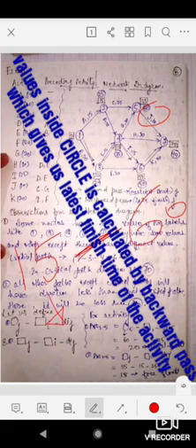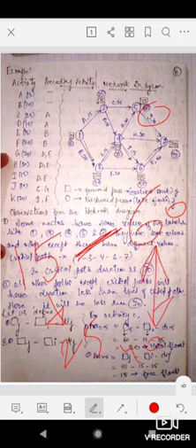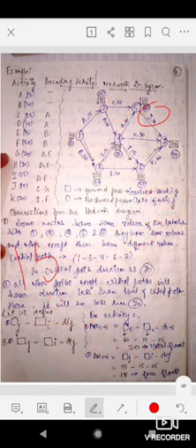So if you start at 15 and it takes 25 days, it will be completed after 40 days: 15 plus 25 is 40. If you complete that job at 40, then you will have 20 extra days remaining. So this is the total float. This is the extra time which is available to us so that we can delay this activity without affecting the project duration.